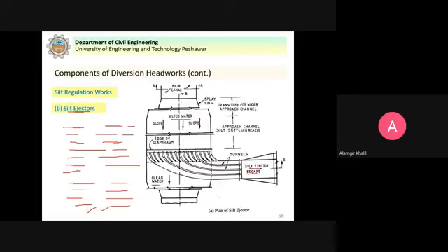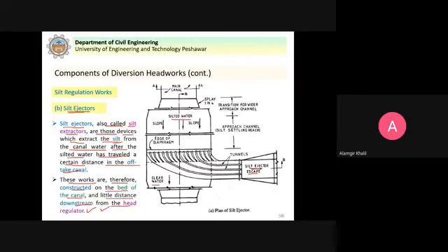So relatively uniform water layers can move in the canal, with the bottom water more silt carrying and the top relatively less silted water, that can be easily and efficiently separated by silt ejectors. So silt ejectors are therefore superior to silt excluders. Silt ejectors are better than the silt excluders.